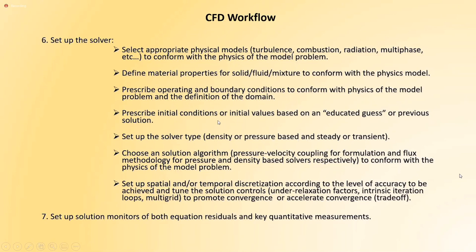Prescribe initial conditions or initial values based on an educated guess or a previous solution. If you don't have a previous solution, there are many ways to initialize the domain. Besides the boundaries, we need some kind of number in every cell.